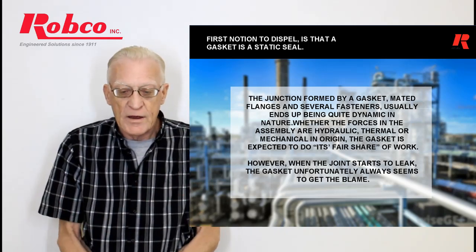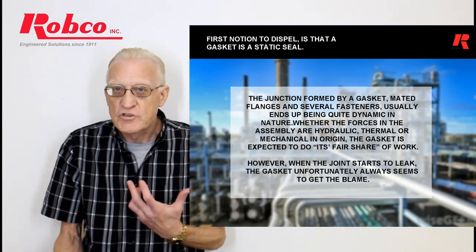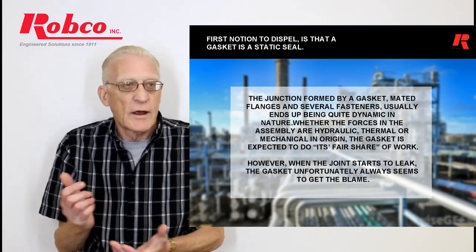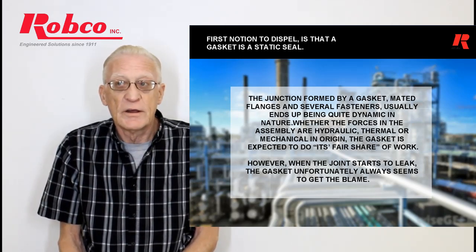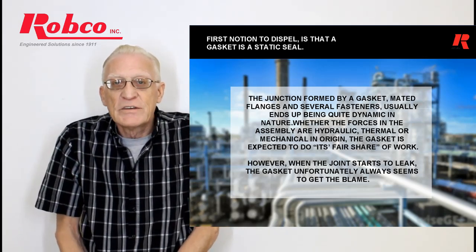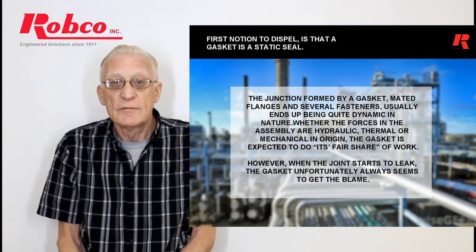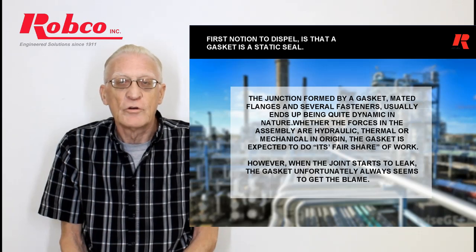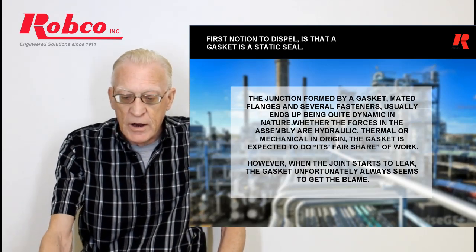The junction formed by a gasket, mating flanges, and several fasteners usually ends up being quite dynamic. Expansion and contraction from heat and cold, water hammers, vibration in the line. Hydrostatic end force, which we'll talk about later, is the actual internal pressure trying to open the two flanges apart. All these things that you don't see, the gasket has to put up with. And of course, when there's a gasket leak, it's the gasket's fault, nothing to do with the bolts or how you installed it. Today we're going to talk about those different things.